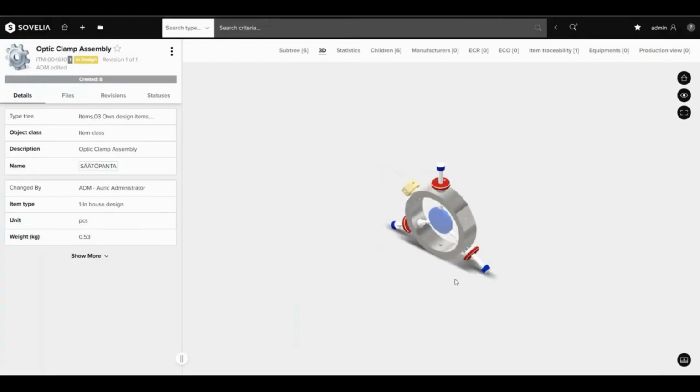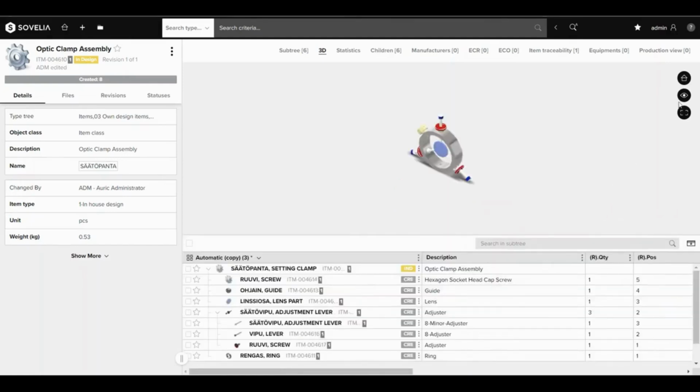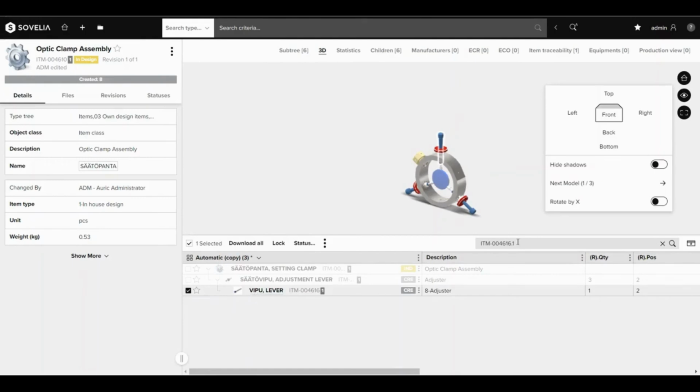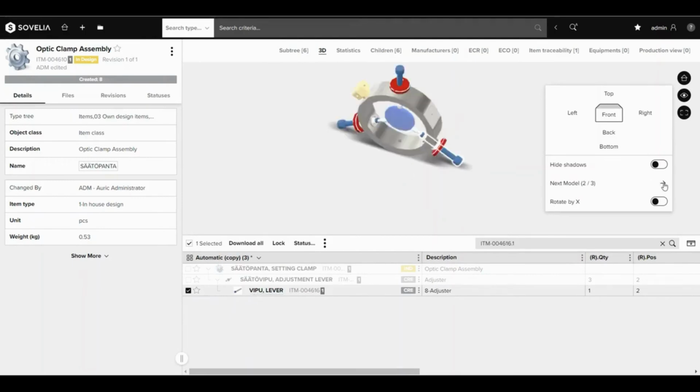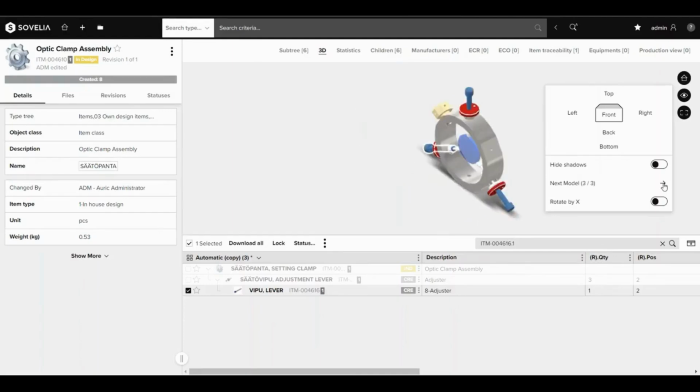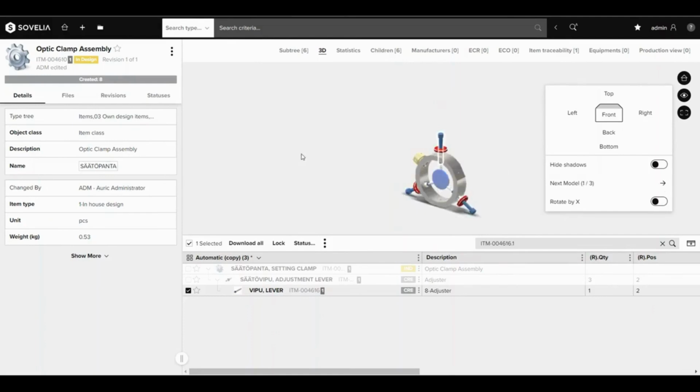If we have multiple of the same parts within the window, let's take a look here. If I was to select, for instance, this piece here now, there are 3 versions of this in the window, and we can see that the 3 appear here, saying that there's 3 different instances of the same model. If I now use the I button, I should be able to cycle through the 3 different options, and it's highlighting the position of those 3 models inside the window. Really handy feature.